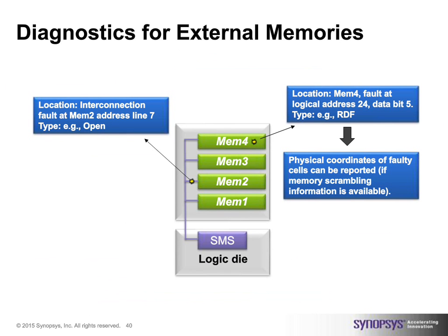So what this solution provides us is the ability to identify which interconnect, identify which memory at the high speed, and that, of course, as a result, finds a good repair solution for it while your DDR port is interacting with the memories or your HBM, and accordingly be able to solve the problem. So FinFET chips, again, do have these kinds of memory issues these days.